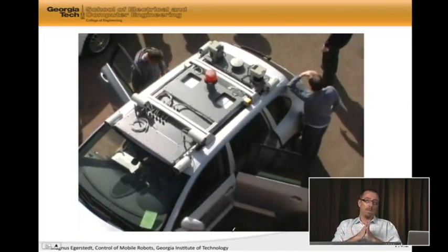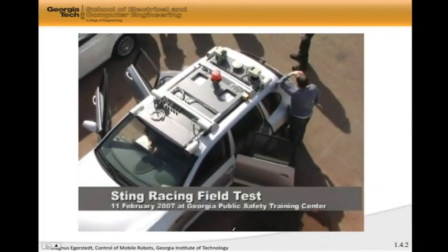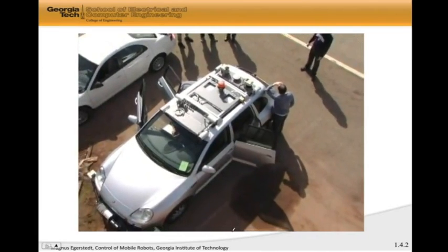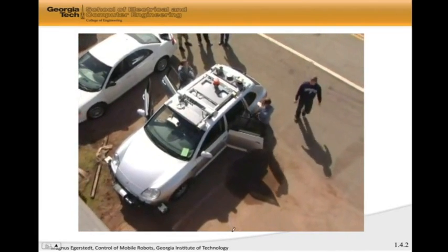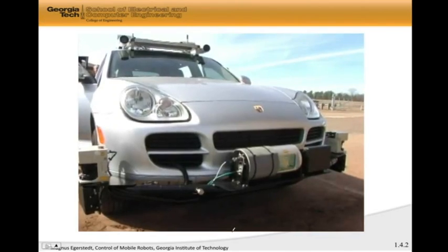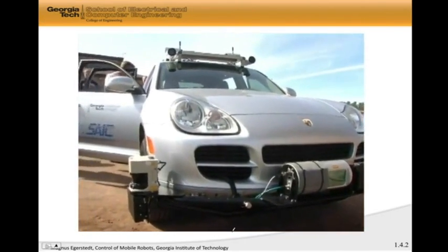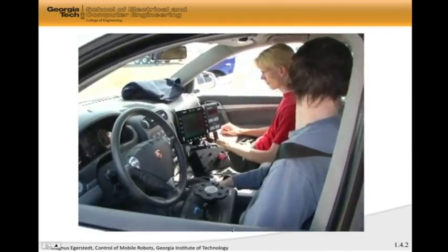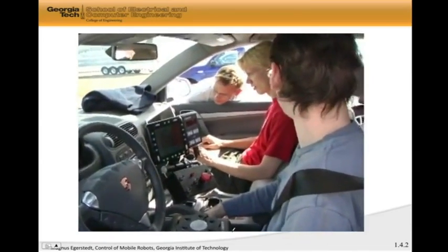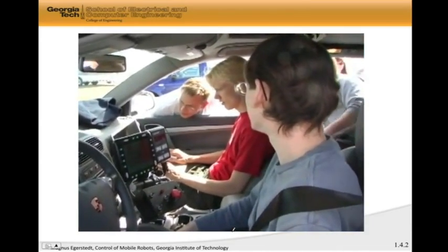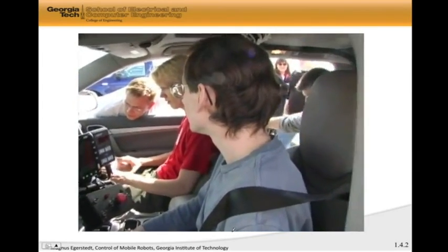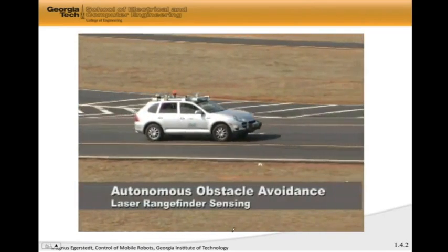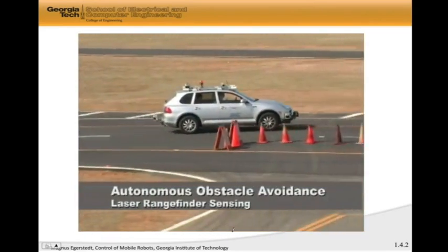I was involved in one of the DARPA Grand Challenges. This was an urban challenge where we were supposed to build self-driving cars, and we used almost exactly this model for our cars. So I want to talk a little bit about how one would do this. Here in the front is a spinning laser scanner. On the side is another laser scanner sitting on top of a radar. These were what we used to get measurements. On the inside is our instrumented car, which translated input voltages into mechanical actions that push down the gas pedal. So this is how we actually affected it, with the same coefficient.